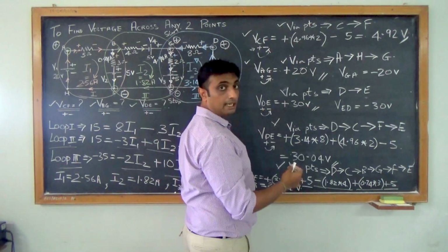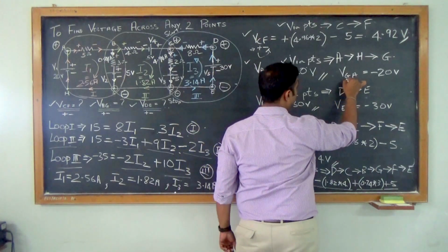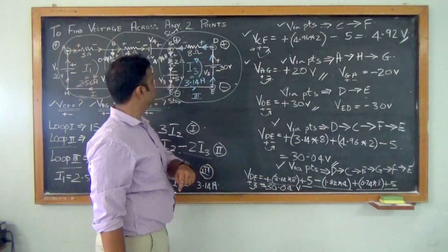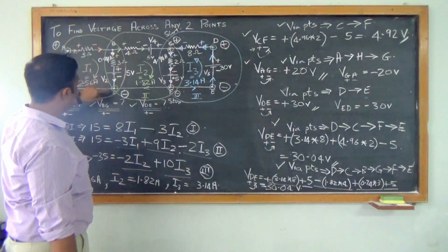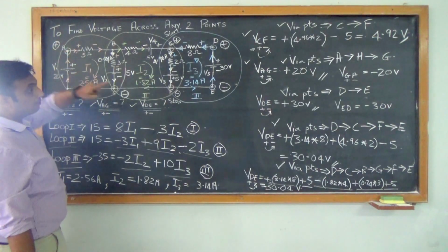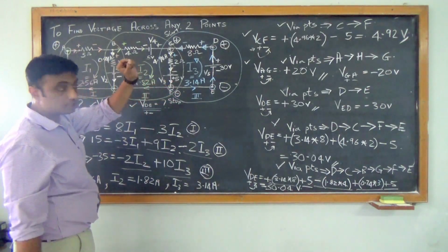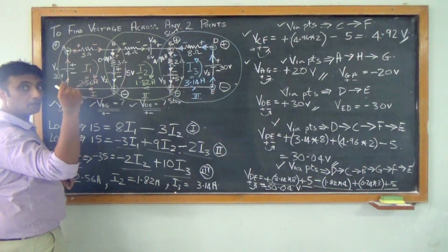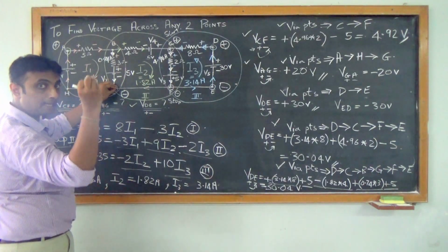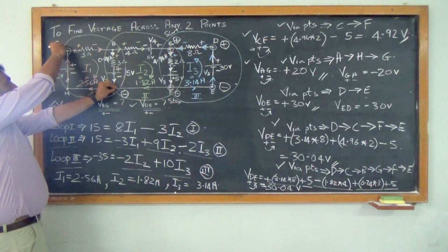It is the same thing as stating your G terminal as positive and A as negative. So if you take GA, I have my G here and I have my A here. If I am taking the first terminal as G, that means the positive terminal of my multimeter is connected here and my negative terminal is connected here.